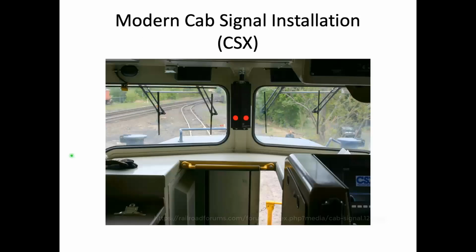And there is a modern, I think that's a CSX locomotive, but that's the cab signal displaying restricting right in the middle of the cab. Union Pacific was an enthusiastic convert to continuous coded cab signal, and its locomotives carry the little forward indication cab signal indicators on the front wall of their cabs to this day. CB&Q opted for a 3 indication version that otherwise looked similar.